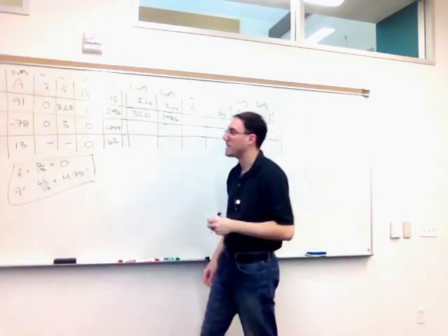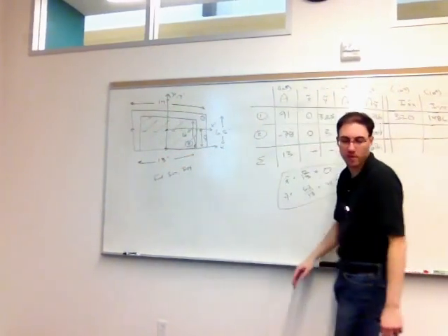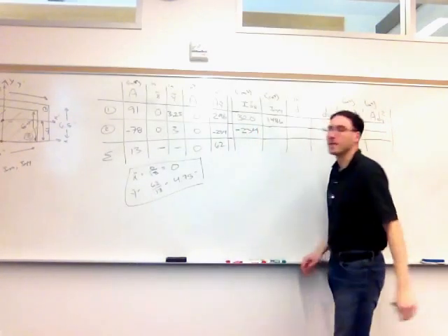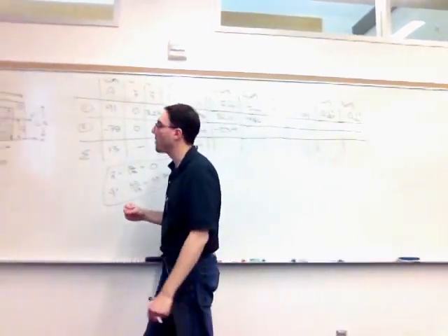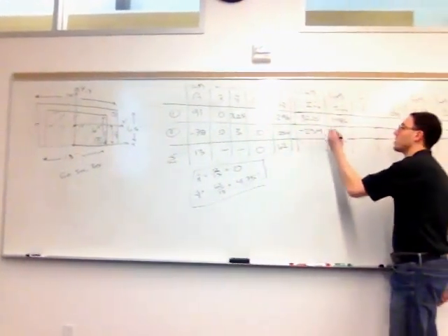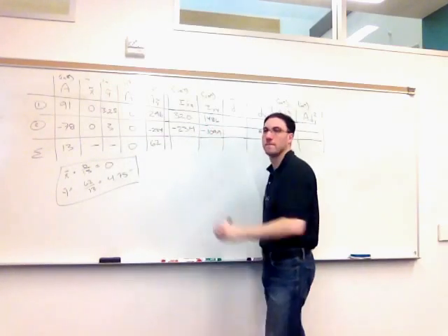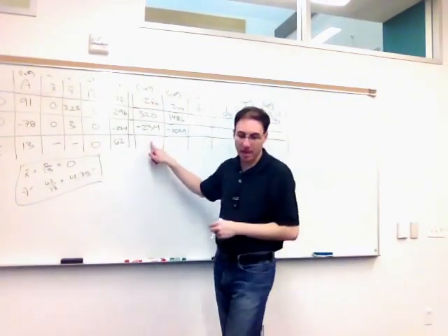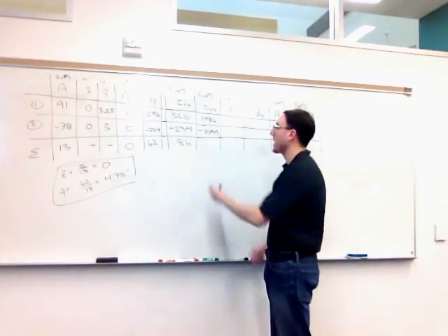Going to shape 2, the same idea about its horizontal axis. It will be 6 cubed times 13 over 12, which will be 234. This is a cutout shape, so this is negative. And for its Iyy prime value, it's the 13 cubed times 6 over 12, also a negative value of 1099. I can add down here, and I will get 86. Adding down here, I get 388.